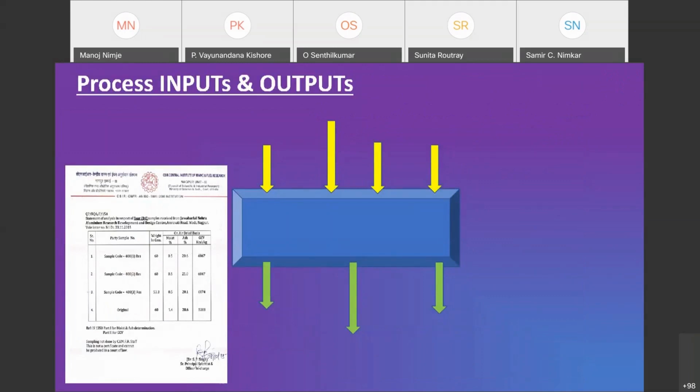Here the inputs to the process are first cut SPL; second, some amount of heat to raise the temperature of SPL to 400 degrees centigrade; the third input is 1:10 amount of water to leach out leachable sodium and fluoride; and the last input is some amount of lime to separate out the leachable fluoride as an insoluble salt of calcium, that is calcium fluoride.